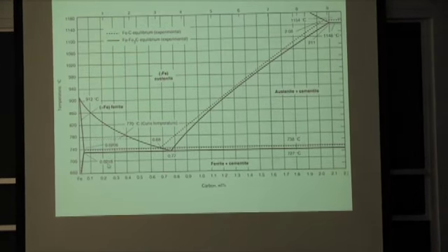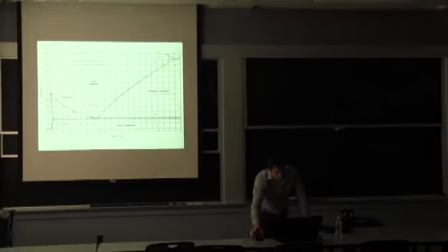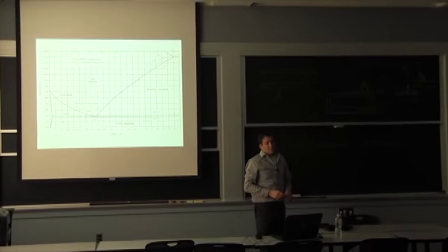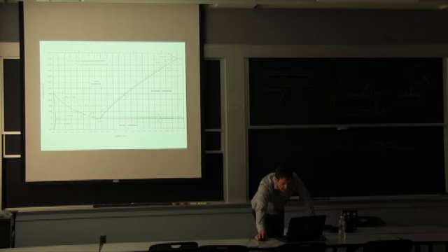Structural steel will tend to be at about 0.2% carbon. I mean, there are different variations, but I'm just going to use that as a starting point. So 0.2 is right here. A lot of structural steel has this composition. You can have higher carbon if you don't have to weld it. And by higher, I know like a 1045 steel, you can make a heat treatment on it and you'll be around this level.